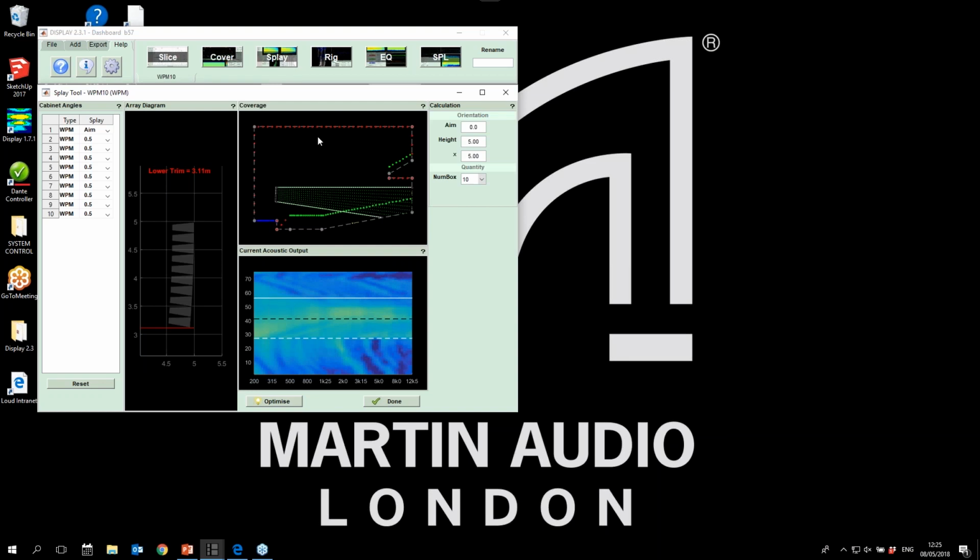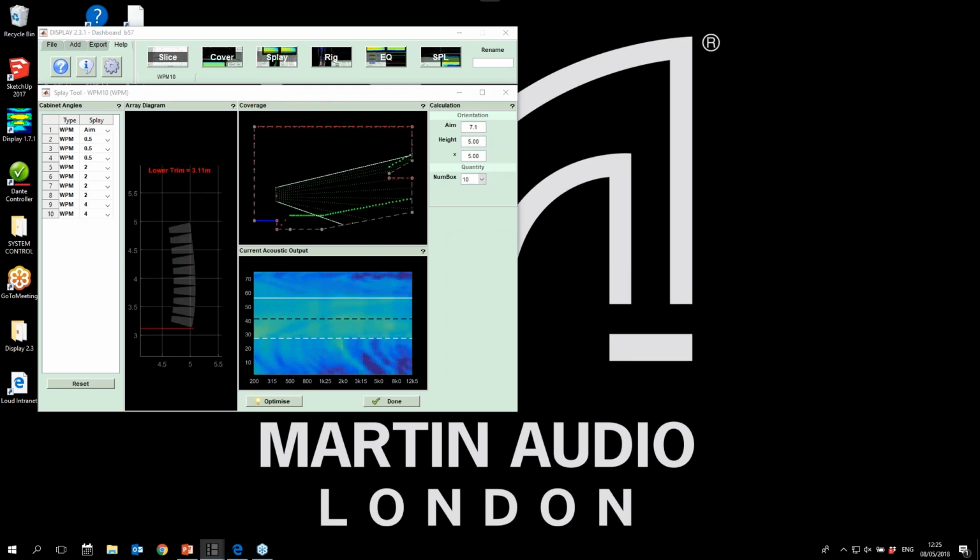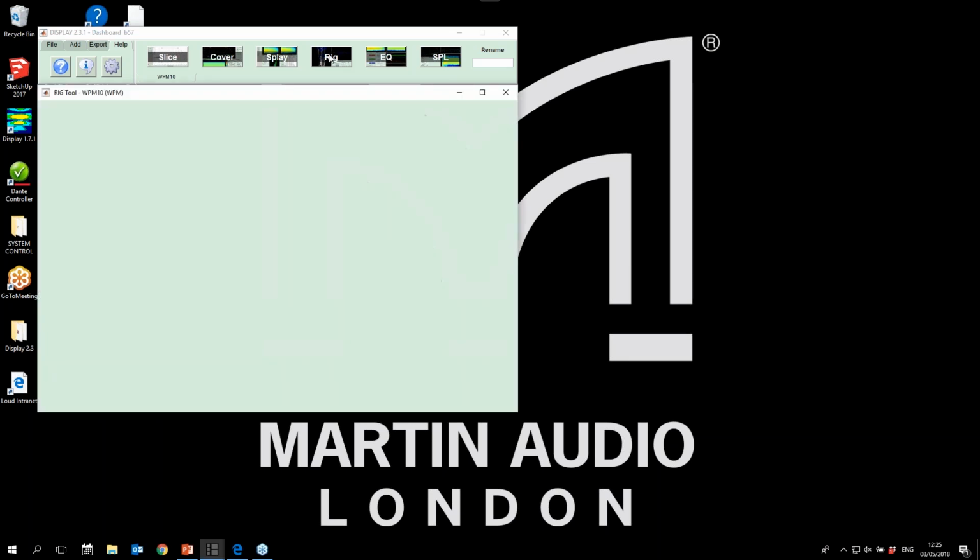So here all we want to do is just hit optimize and watch the array mechanically optimize. You'll see there it does a little dance whilst it works out the optimum angles. And we can see that it's covered the venue pretty well within its parameters. So all we do now is we click done and move on to the rigging page.